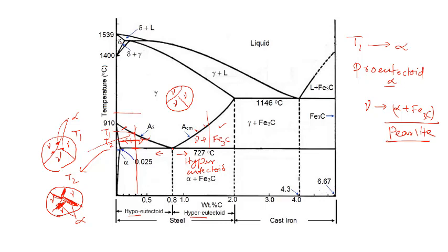Okay. So the cementite phase is first going to nucleate from the gamma phase, and then as you lower the temperature, the fraction of this cementite phase would increase, and as you come down to the eutectoid temperature, the remaining gamma phase will transform into pearlite. Okay, and in the final microstructure, therefore, you would see this pro-eutectoid cementite along with the pearlite, in a similar manner to the hypo-eutectoid case.